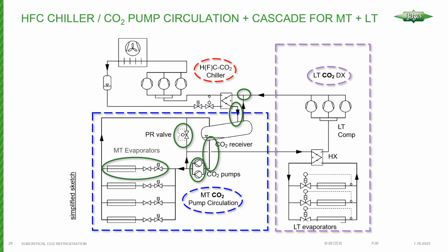But note that as the evaporators start satisfying, so they meet the load and there's no longer a requirement for refrigeration, the valve will close on that circuit. As the valves close, the pressure leaving the pump side is getting greater and greater. So that would be the purpose of this relief valve. That's what they're showing here. The relief valve then would vent the excess back into the receiver, so it's available for any other evaporators that require refrigerant.